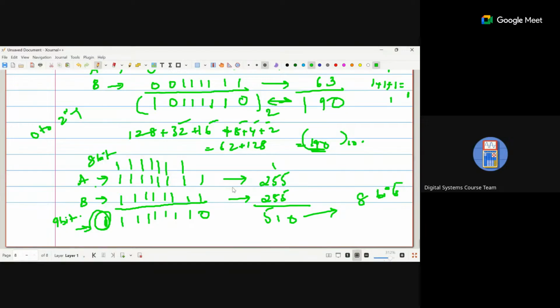So you can keep this in mind for now, that whenever you are adding two numbers, and not just the maximum number, even if you had, let's say, 253 and 255, it will still exceed, because the range of your 8-bit number is within 0 to 2 power n minus 1. So it will still exceed the maximum value of the 8 bit. That way overflow occurs, and only at this point we will introduce sign extending and adding.